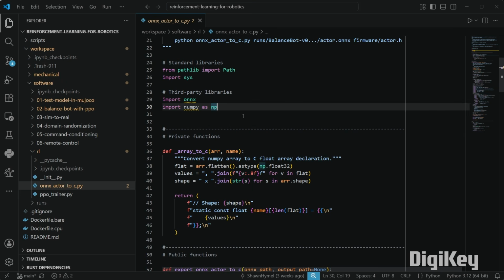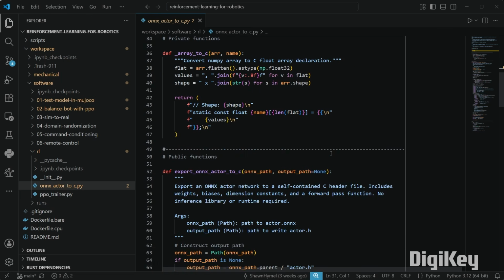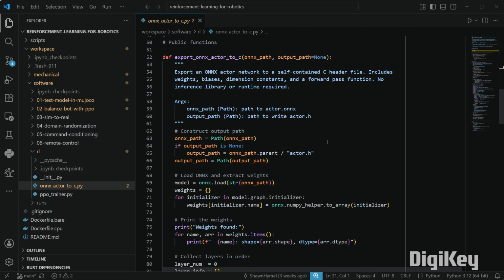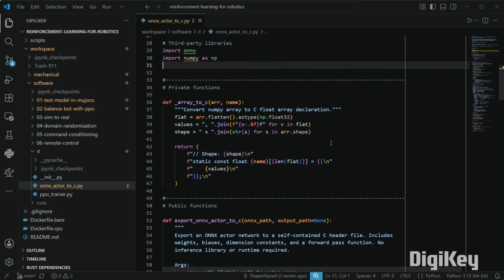There's no acceleration for this, but rather than trying to stand up TensorFlow Lite for Micros, we're just doing basic multiply and accumulates with a tanh activation function. Turns out that's pretty simple to do in C code, and the actors are generally small enough we can run them in 2 to 3 milliseconds just through the very fast CPU that's on the ESP32. This works just fine.